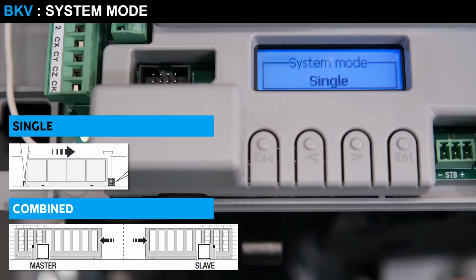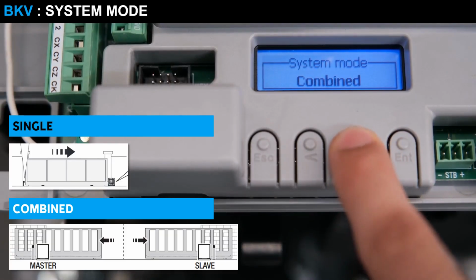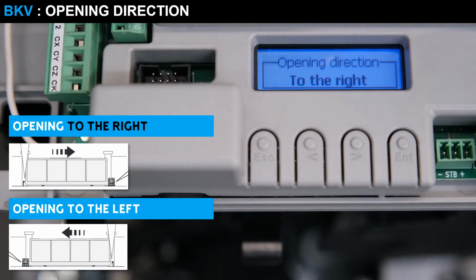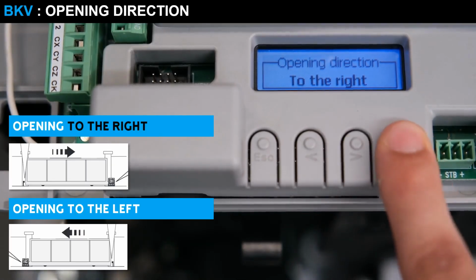The first parameter to configure is the type of system. This defines whether the gate is composed of a single or double leaf. In the case of a double leaf, 2 automations will be needed. The opening direction allows you to set whether the gate opens to the right or to the left. In our case it opens to the right.